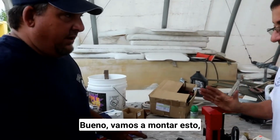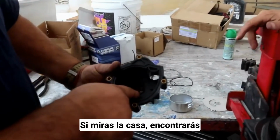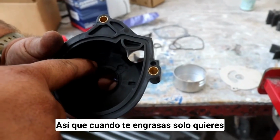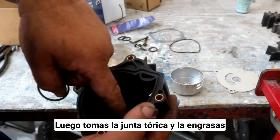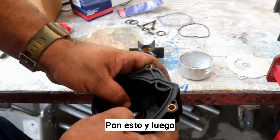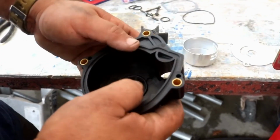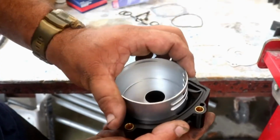So we're going to assemble this. If you look in the housing, you have the O-ring, and there's a weep hole. You never want to put grease there. You only put the grease down here. Then you take the O-ring, put grease here, and put this in, and it secures it. The only reason I'm putting grease there is to secure it. Once it's secured, you put grease around here for the wear plate.